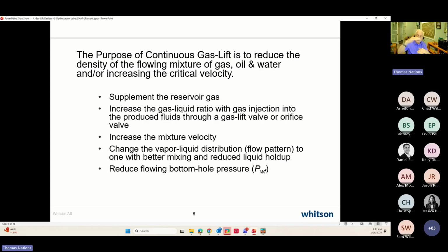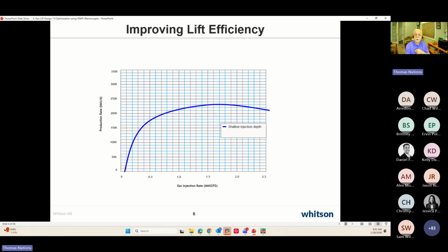So if you take a 1 foot section in the tubing in the well and calculate the liquid and gas in that, the amount of liquid and the amount of gas, that percentage of liquid in there is the liquid holdup. So of course the objective of this artificial lift method of gas lift is to reduce the flowing bottom hole pressure.